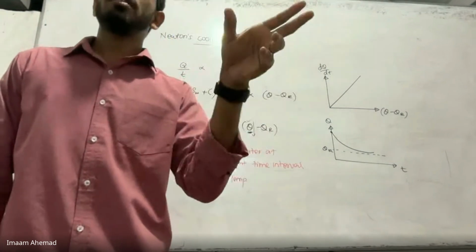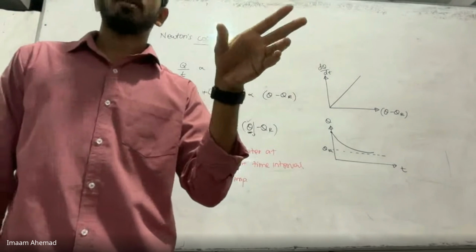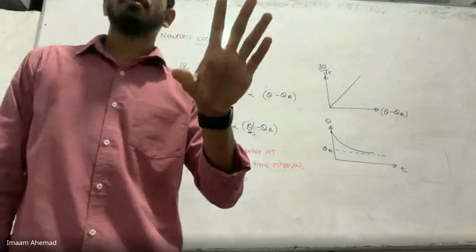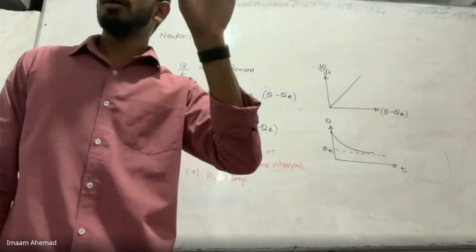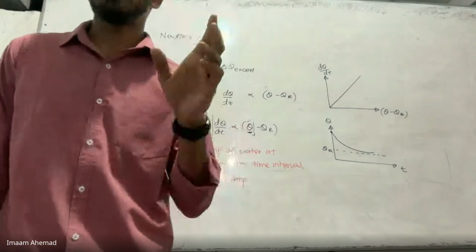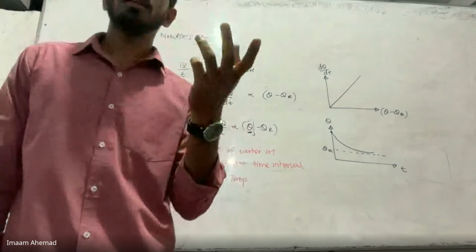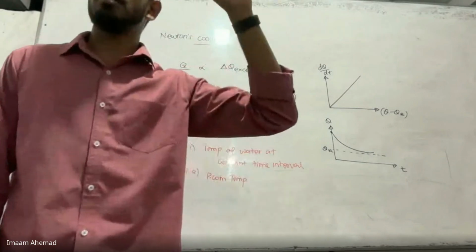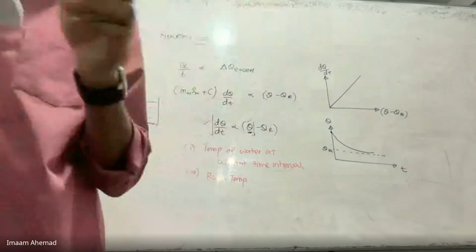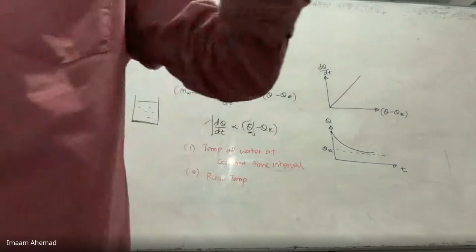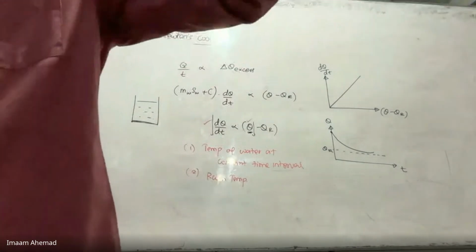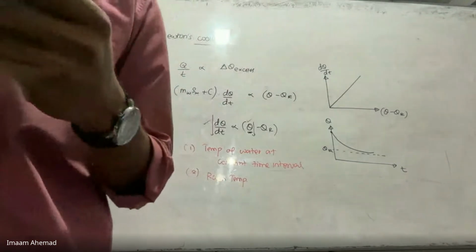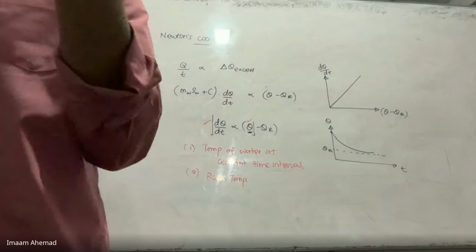In natural convection, what is the condition? Excess temperature should not be greater than 30. Okay, for natural convection, excess temperature should not be greater than 30. For forced convection, any excess temperature. So remember that point. Then placing it close to an open window, placing it next to a fan is better. Why is that? We can get a uniform airflow than close to a window. Okay.